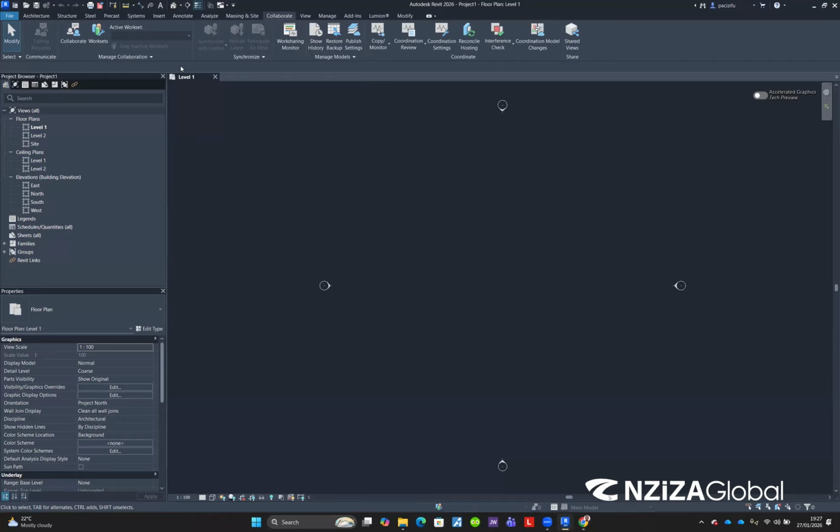If it's structural, mechanical, HVAC, if we are working together in one file, we just use this one, because it's where we have to synchronize our files. When you update your files, like if you change the wall or anything in the design, we need to synchronize that design. Then other people will see those changes in their files.